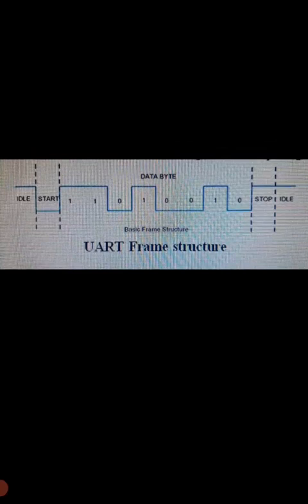The features of UART1 are 16-byte receiver and transmitter FIFOs, and a built-in fractional baud rate generator with auto-bauding capabilities. In UART1, software and hardware flow control implementation is possible, and the standard modem interface signals are included, with the flow control fully supported in hardware.